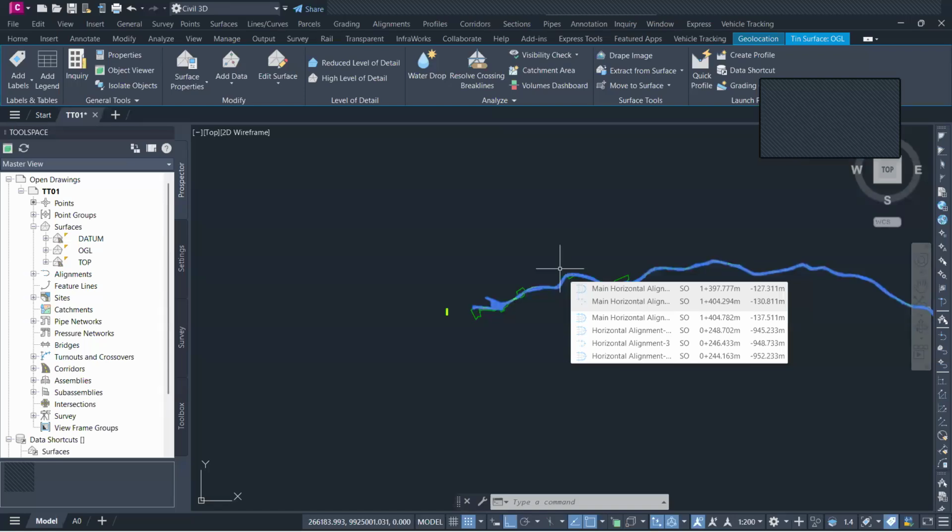Site clearance will be length times width of the section. So let's say the width is again the road corridor. Sometimes you don't do site clearance for the entire corridor because, let's say, it was an existing road. So if it is an existing road, you know that there is a width of, let's say, 7 meters.